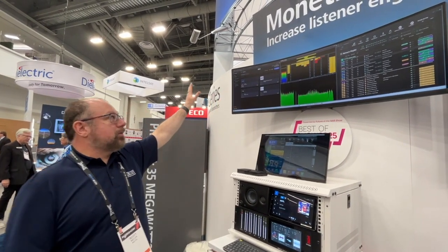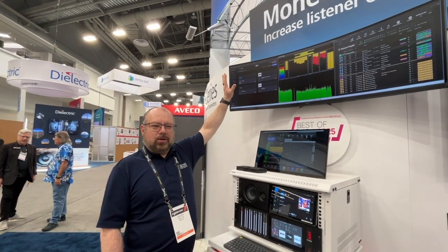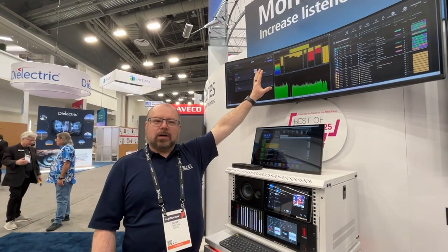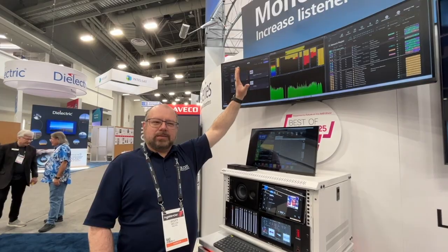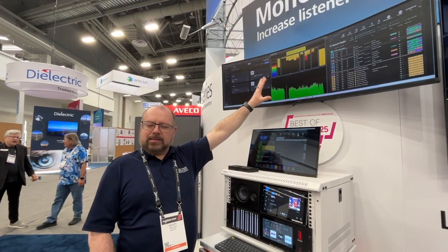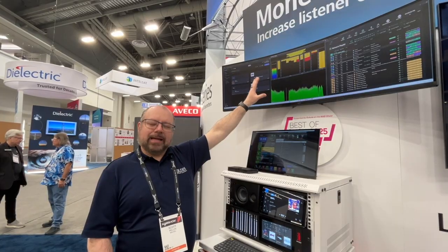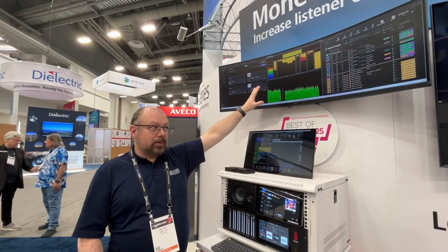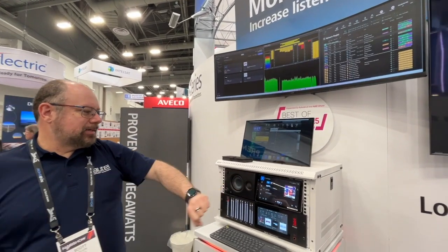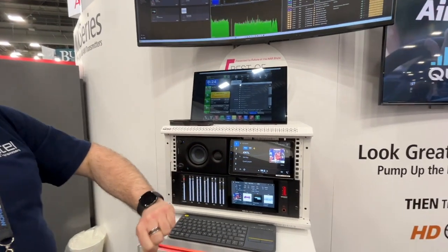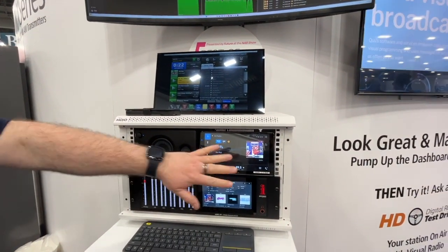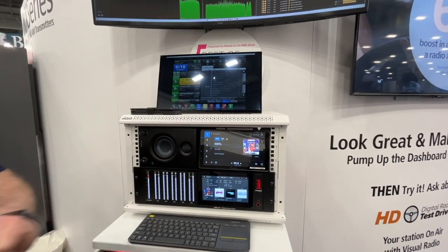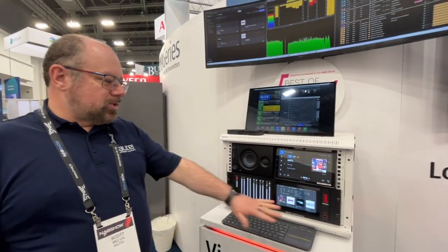It's receiving it. So right now we're receiving 4 different streams, 1 from Wide Orbit and 3 from Radio Cloud, all at the same time. It's then passed to our Omnia for Nautel audio processor that's built into the transmitter as well, running again in a virtual platform. It's gathering that data from Rapid and generating the album art that's being sent out to the transmitter. And you can see here we've got basically a car radio receiver we're using. This is currently receiving HD1. So we've got the album art, we've got our song title and information. I've also got the Inovonics up here just as a reference to show the other information.